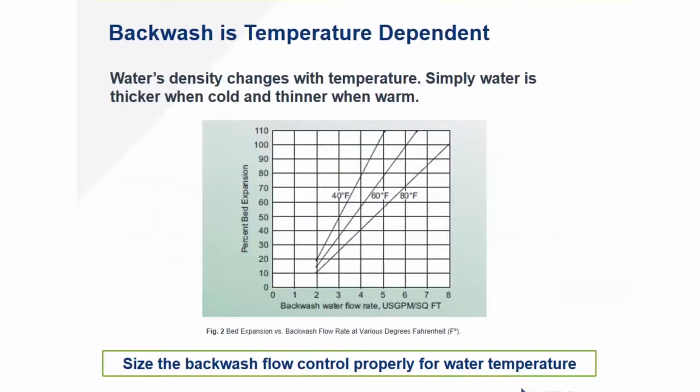I was starting to see some iron break through the bed coming out my taps at various faucets in the house, and this was just out of the blue. And this was a simple change: 2 more minutes on my backwash, problem goes away. The other thing is you want to make sure your backwash or your drain line flow control matches the rate you've selected.